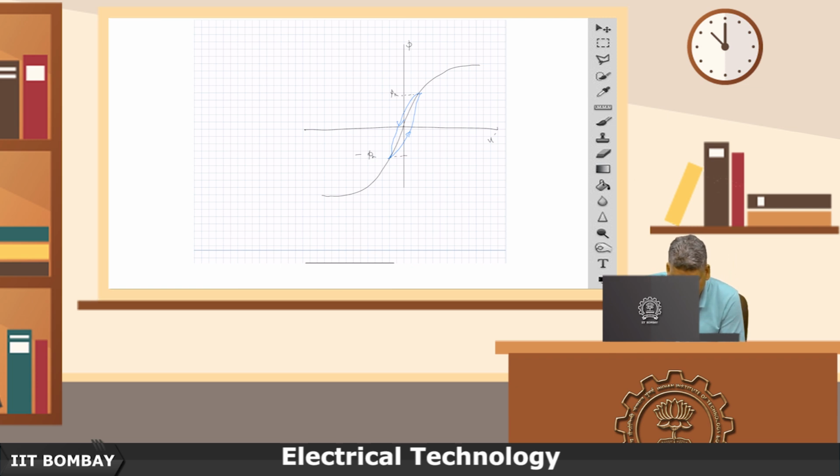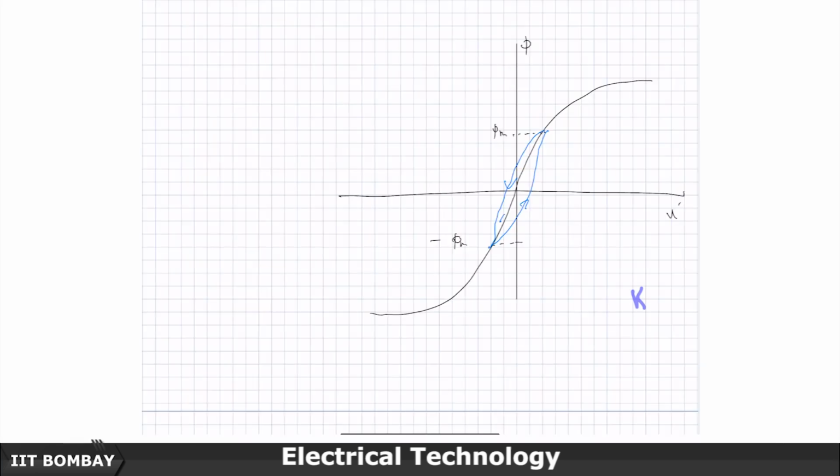Here, what we have done now is basically we have said that this is the work done. If you talk in terms of B and H, then the integral, the area under this, is, I think we did this per unit volume, this is the work done, or per unit kg. I think it is per unit volume we had derived that, and this creates a loss component.